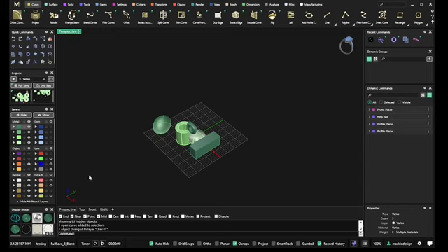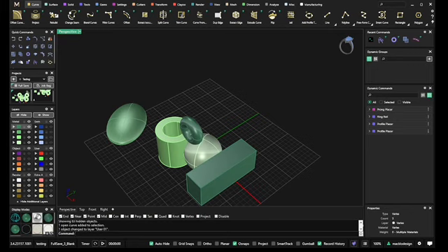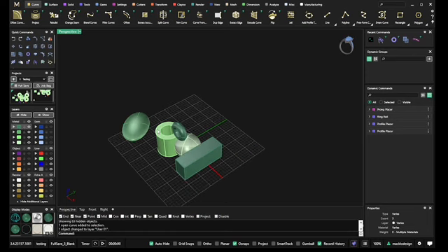There's a pop-up here that says cannot hide current layer. What does that mean? Well, what that means is that I have dark green, not only as the default, but I actually have it selected so that anything I create is going to come in on the dark green. How do you know that? Well, I don't know if you can see it, but there is sort of a frosted panel over that dark green color. How do you change that?